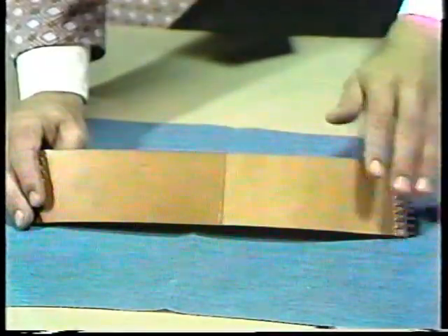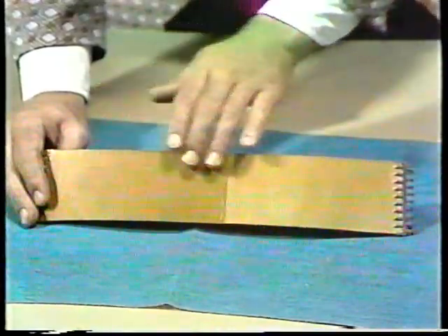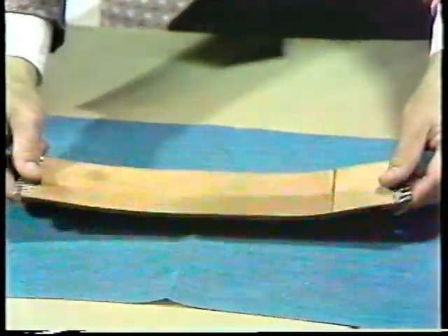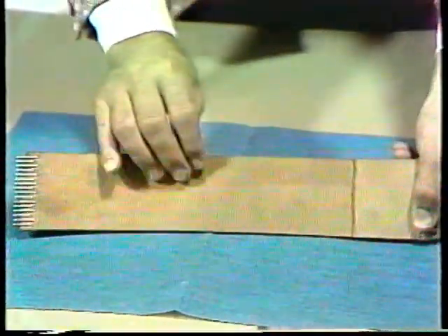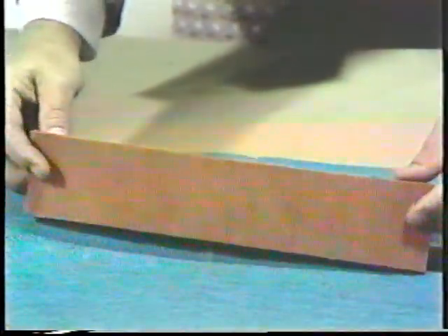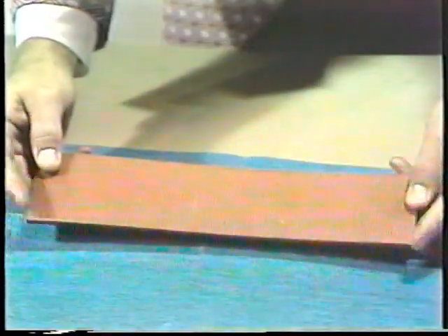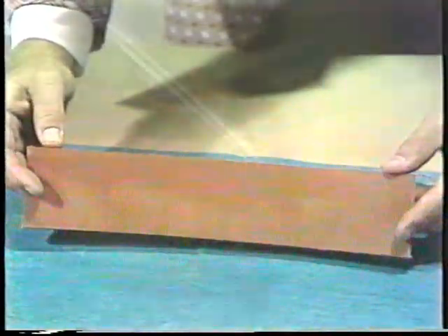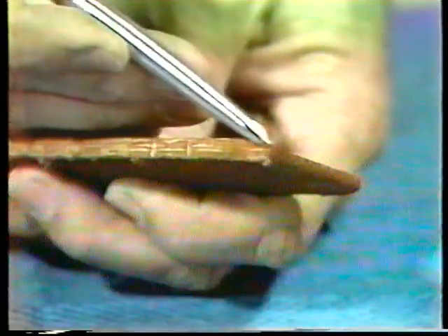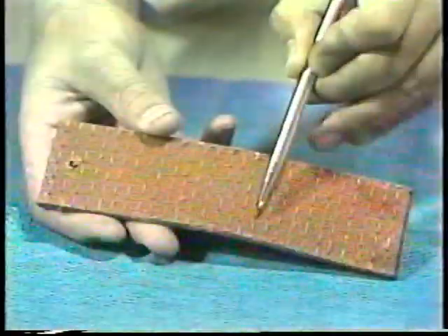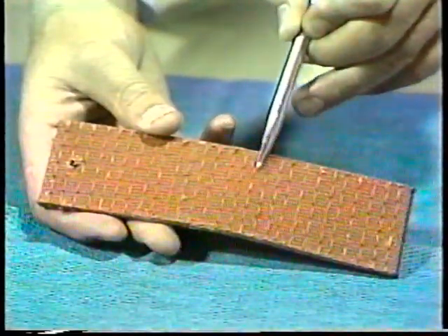In the past, leather has been used extensively in flat belts. Today, however, most flat belts are manufactured from rubber, natural fiber, and synthetic materials. A rubber belt, for example, is normally constructed by coating canvas with rubber. The coated canvas is combined with alternate layers of rubber sheeting, then vulcanized to produce the belt. If the edges are wrapped around the canvas, the belt is called folded edge. But if the edges are left ragged, then trimmed back to make them square, the belt is identified as raw edge. The canvas provides strength when the belt is under tension.